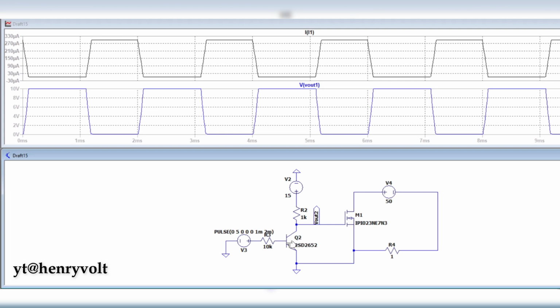Since this transistor is an NPN and is used as a switch, the simulation is already run. So let's see the input voltage. The input is oscillating between 0 and 5 volt, and I'm using a 15 volt power supply through an auxiliary power supply, which is connected here. I have kept 1K because I don't want too much resistance in it, and there is also a trade-off between power loss and other things.